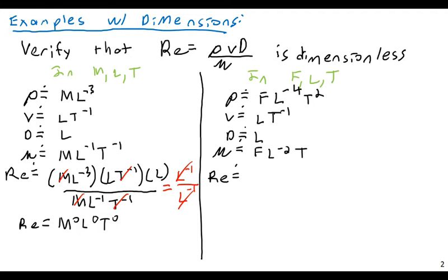Now, this does not mean that the Reynolds number itself has no number. It does have a number. It can have a value; we can actually calculate the Reynolds number for a given fluid flow. If you have a fluid that's going through a pipe of a certain diameter with a certain viscosity, a certain density, etc., you can calculate the Reynolds number, but that number is dimensionless. And as we'll see later on, it being dimensionless gives it certain abilities and certain properties that are special, and we shall see that.